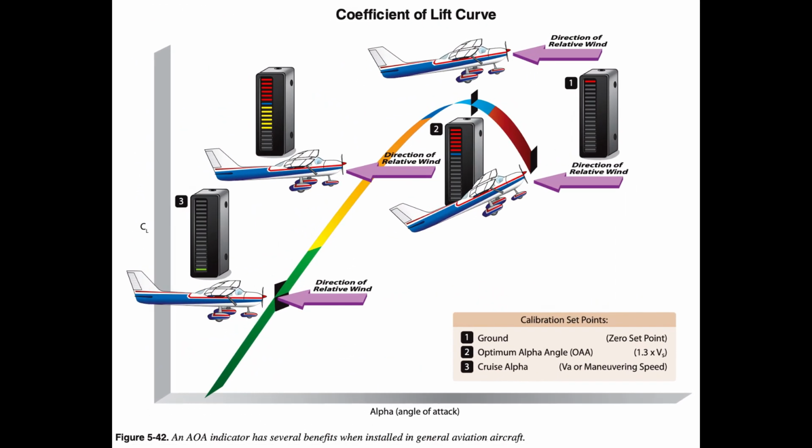This can also be referred to as stall margin awareness. More simply explained, it is the margin that exists between the current AOA that the airfoil is operating at and the AOA at which the airfoil will stall, critical AOA. Angle of attack is taught to student pilots as theory in ground training. When beginning flight training, students typically rely solely on airspeed and the published 1g stall speed to avoid stalls. This creates problems since this speed is only valid when the following conditions are met.